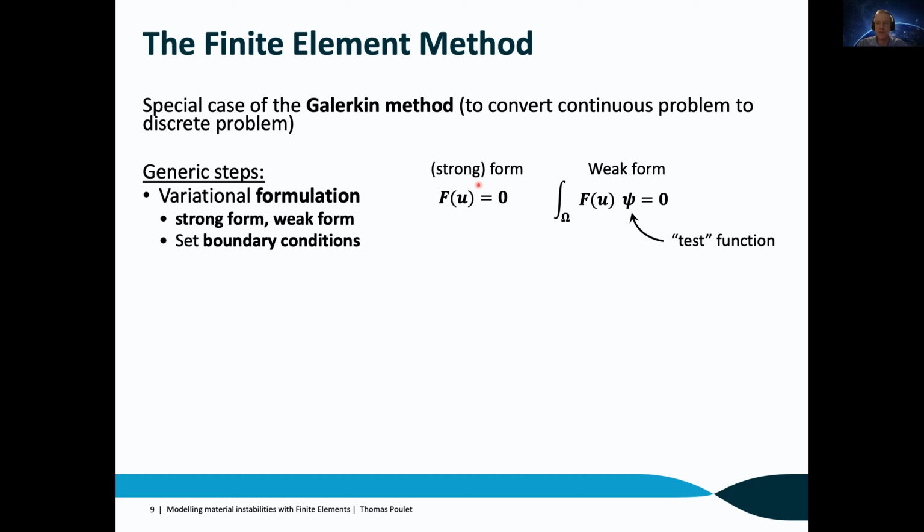In particular, if you've got partial differential equations, you will need, let's say, a Dirichlet boundary condition to set the value of your unknown, for example. At that stage, you've got your formulation. We now need a discretization strategy. So it starts with creating a mesh, and this is a geometrical problem.